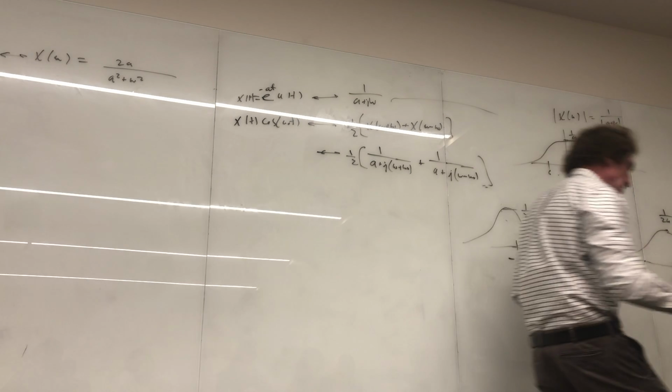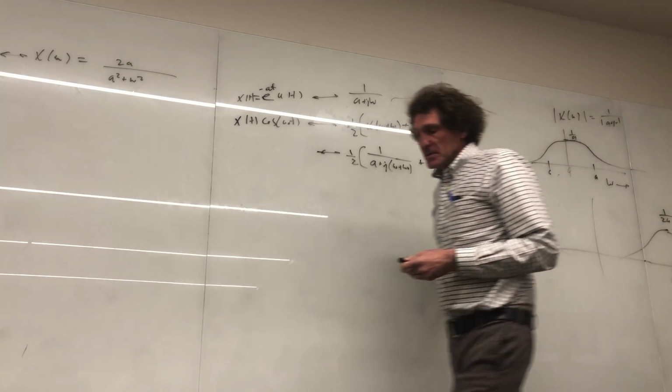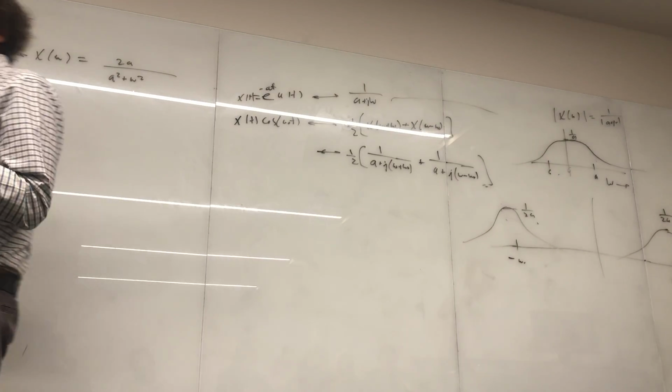Now what it did is took the low frequency signal. It's important to see. It took the low frequency spectrum here and it shifted it and stuck it out at plus or minus omega naught. Do you all see that? That becomes critical. And that's exactly what happens with AM modulation. So for AM radio stations, they're at hundreds of kilohertz, right?